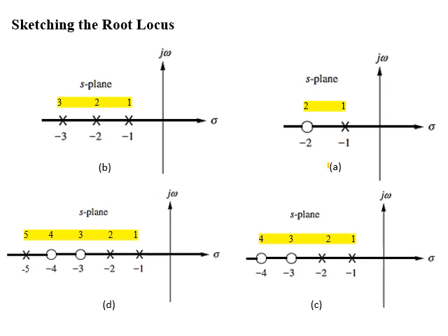Now if you look at figure A, in this we have one open loop system finite pole and one open loop system finite zero. And now if we start numbering the poles or zeros, then as per the rule the root locus will exist to the left of the pole at location -1 or to the right of the zero at location -2.